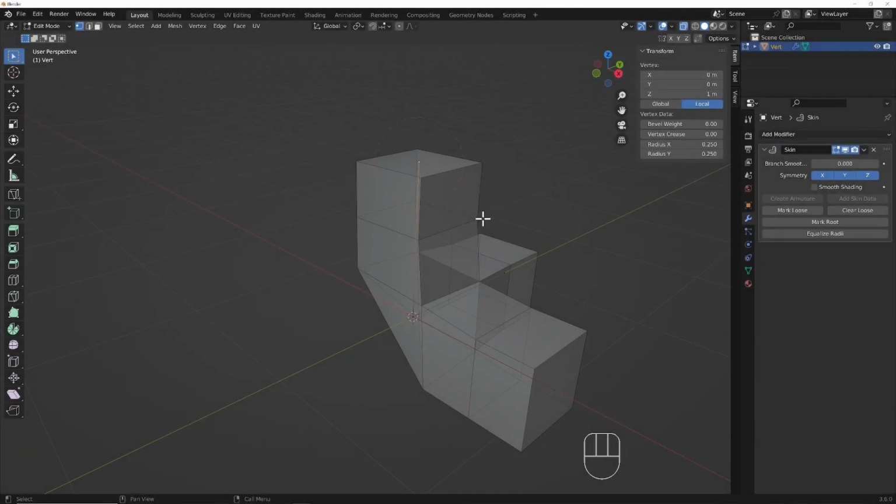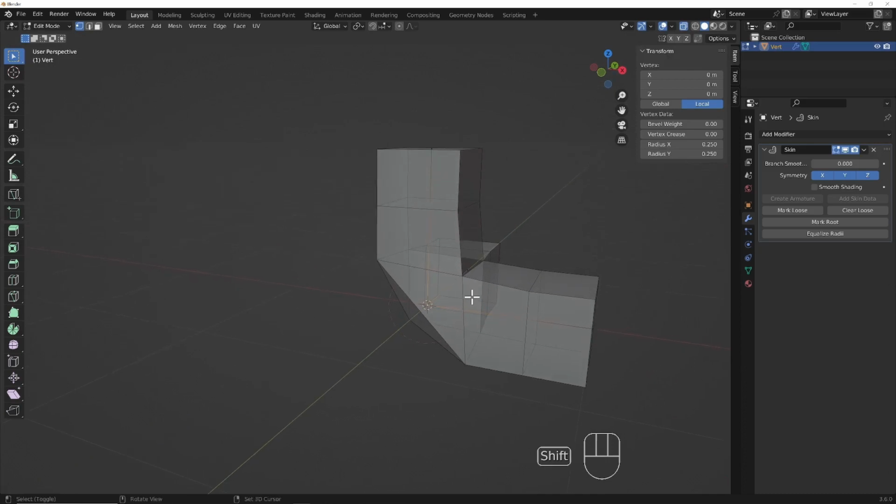You may have noticed this red dotted line around one vertex in particular. Depending on the order in which you may have extruded out branching vertices, this might not be sitting at the original vertex. You can select any vertex you wish and mark it as root. Doing this impacts the kind of armature that is created when we click on the Create Armature button.